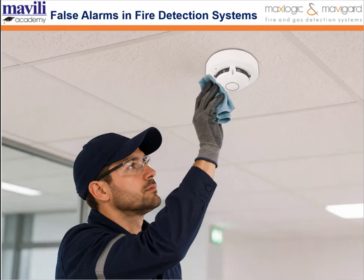Detectors that do not undergo periodic maintenance may detect a real fire later, and the probability of generating false alarms also increases. Therefore, cleaning the detectors, performing functional tests, examining the alarm and fault logs, and checking the system in accordance with the relevant standards at certain intervals are of great importance in preventing false alarms. So we should take this seriously.